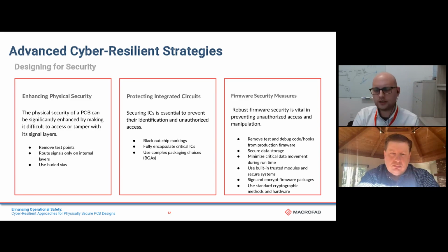Using secure data storage, again, similarly, if you're offloading your storage outside of your main microcontroller to another device, it's a lot easier to intercept that data in flight, or to have other attack vectors that are easier to get at, that don't require as expensive equipment or more complicated methods to attack. You'll see this happened with a recent Bitcoin hardware wallet hack where they were able to get the secret keys while they were being moved at startup during runtime. And so trying to reduce the amount that you're actually accessing and moving the data around during runtime can also help prevent data potentially moving into unsecured sectors, things like that.